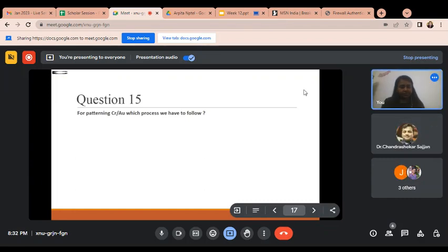we have to etch the substrate. Yes, ma'am. Etching, we have to etch the deposited material. Like if it is chromium and gold, first we deposited the chromium, then over this chromium we deposited the gold. So when in the front side we want to etch this chromium gold, first we have to etch the gold, then below the chromium. So first we will use the gold etchant, then we will use the chromium etchant. Okay.